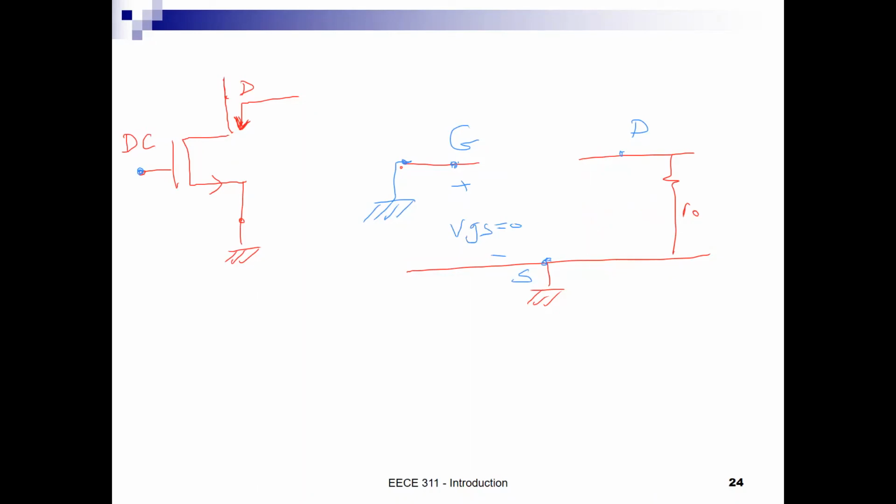Great. So if I bring a supply Vx that is going to interface my circuit here, the resistance seen looking into the drain, this is the drain node, what do I see? What is the resistance that I see looking into the drain node? RO. I see RO. So if a transistor has the gate biased at DC and the source grounded, looking into the drain, the effective resistance is really RO of the transistor. Okay, so we will see it on a slide.